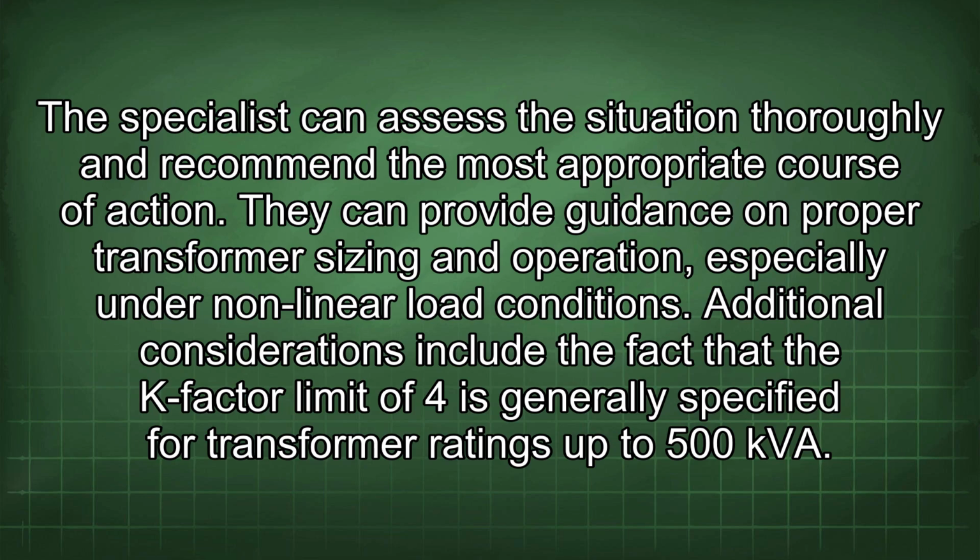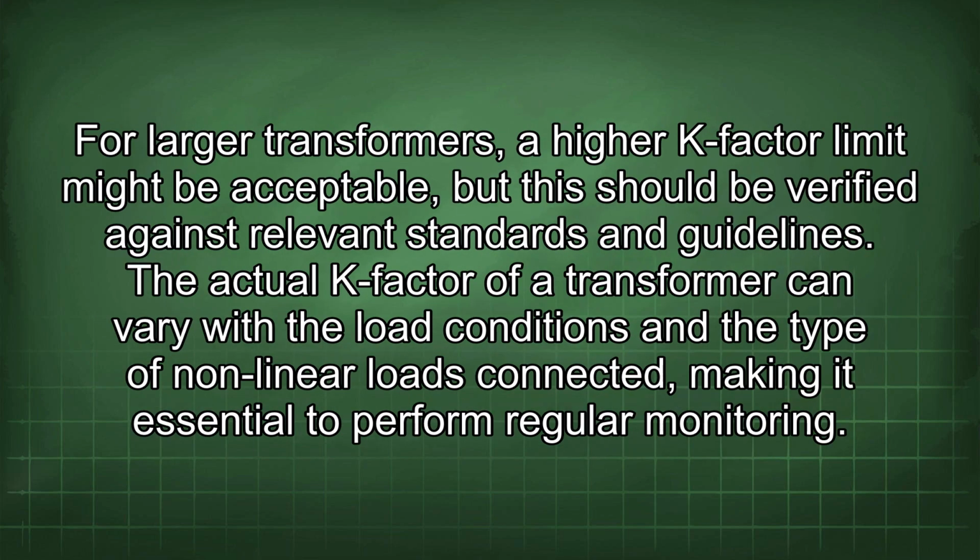Additional considerations include the fact that the K-factor limit of 4 is generally specified for transformer ratings up to 500 kVA. For larger transformers, a higher K-factor limit might be acceptable, but this should be verified against relevant standards and guidelines. The actual K-factor of a transformer can vary with the load conditions and the type of nonlinear loads connected, making it essential to perform regular monitoring.